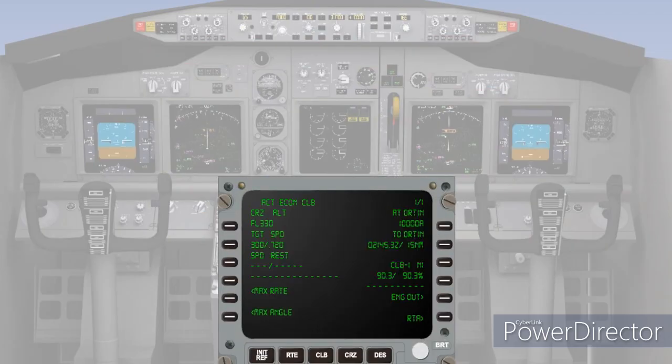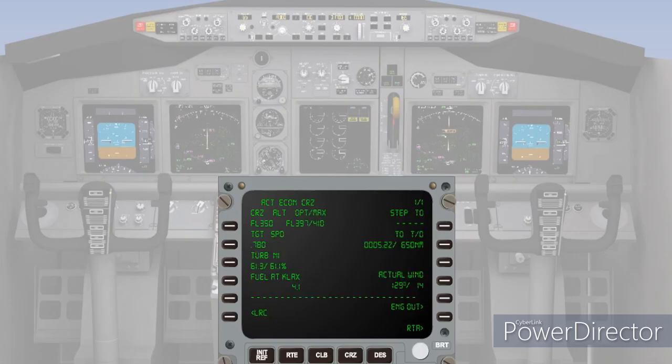Lastly, we will carry out the same climb using the vertical navigation function of the flight management system. As well as the navigation information, the flight management system also holds performance data for the engines and aircraft, and has the ability to provide vertical guidance for the aircraft throughout the whole flight profile. It can provide target values of indicated airspeed, Mach and thrust for optimum control regarding a selected performance mode. For example, economy climb, economy cruise, or long-range cruise.